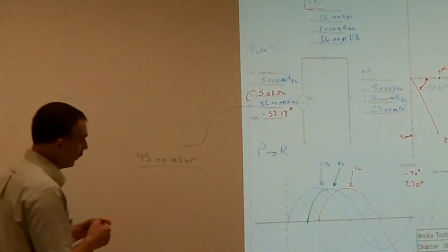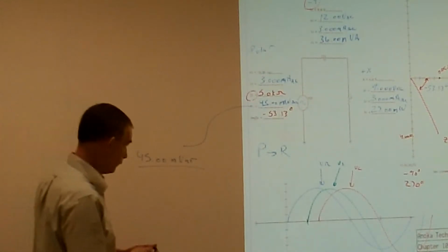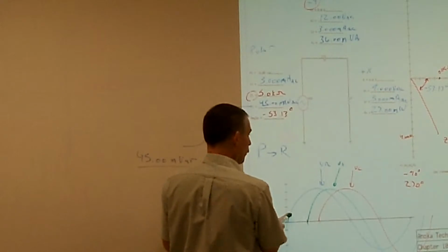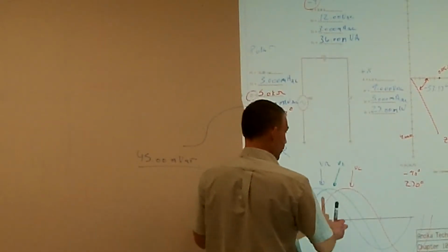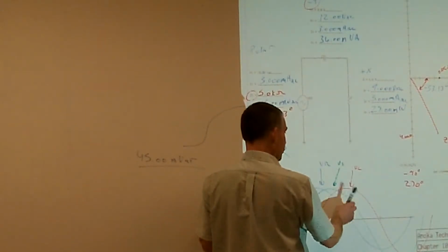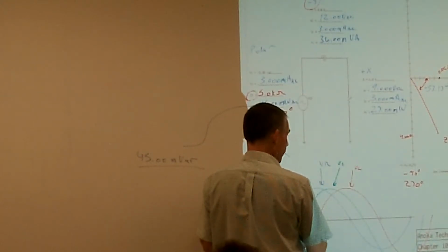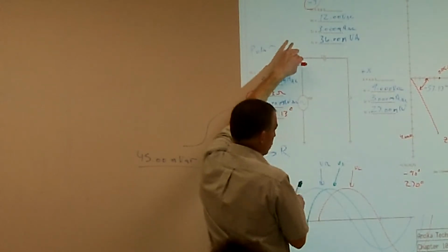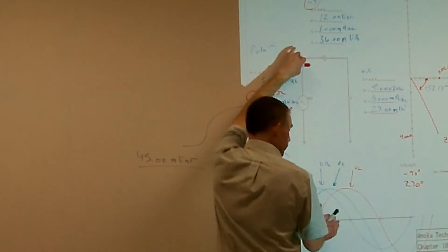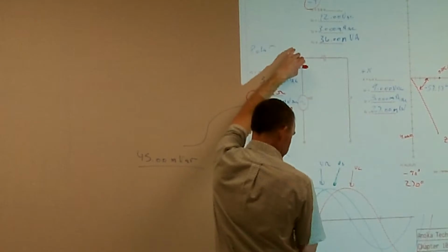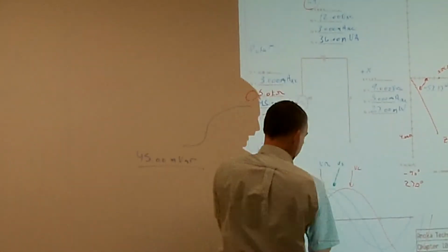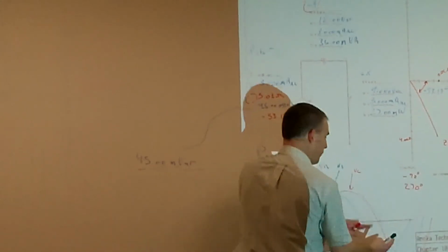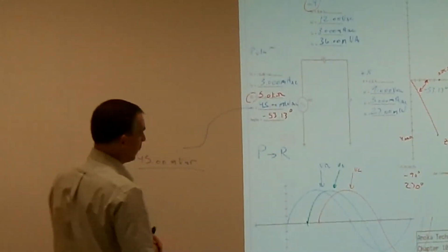So if I were to hook up an oscilloscope, and I put channel 1 on VR, and I put my probe on VS, I would see two of these phases, and I could see that phase shift coming out of there. I would be able to see these two different voltages happening at different times going through my circuit.